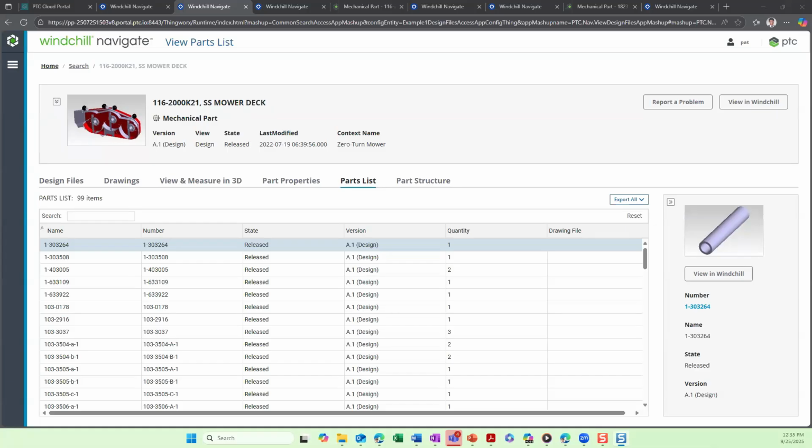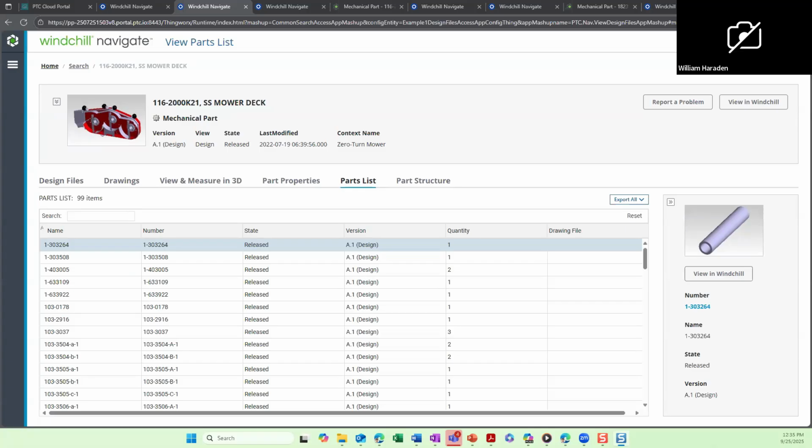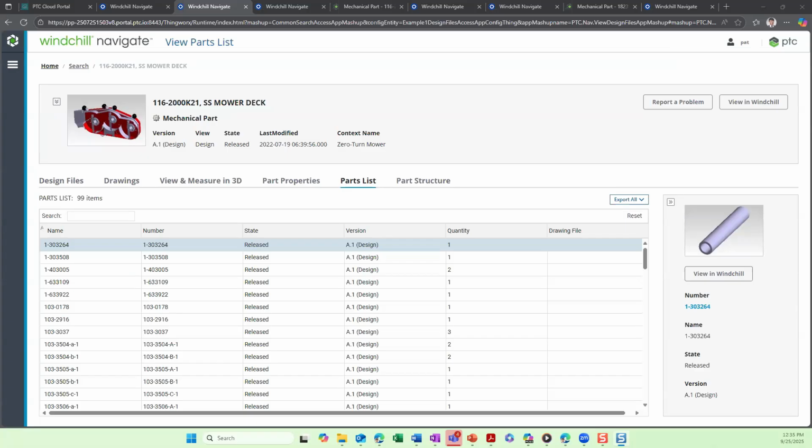If you've got in work or prototype or whatever you have for your life cycle states, it's utilizing your Windchill implementation life cycle states. And then can we implement those into the change request system, at different states or different effectivity? Let's say someone wants a change on something, but it's sitting on other change requests and things like that. Can we utilize those states? Yeah, and just putting a definition together on how those transition from state to state, depending on your change process. That's the two pieces that we need to figure out.